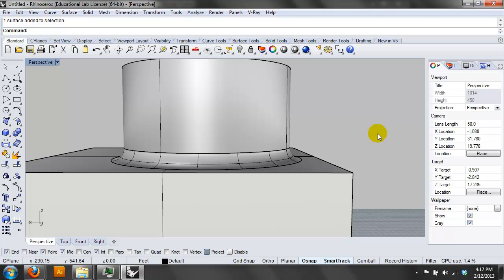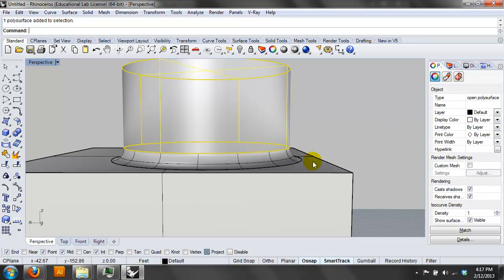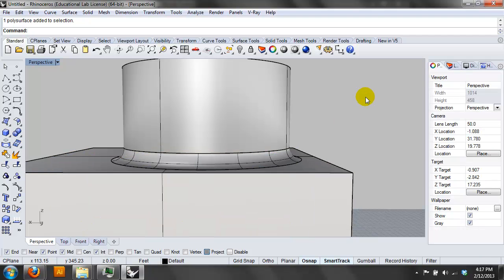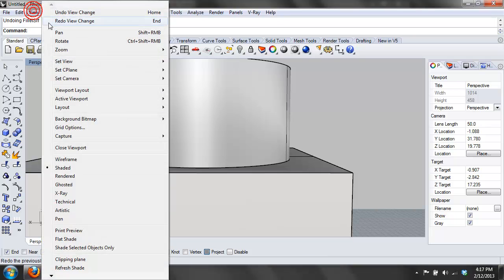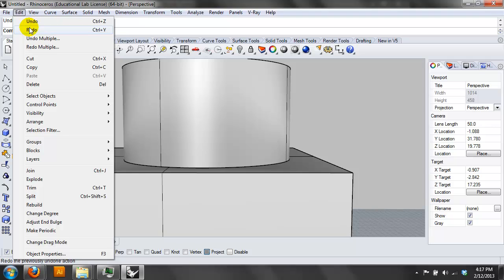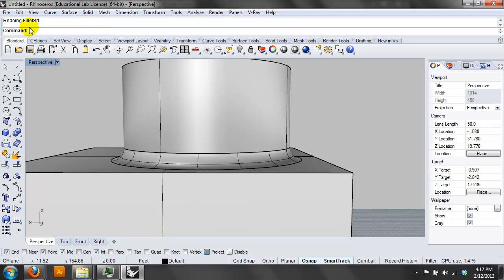What did we just look at before? Yeah, sweep it. Do a 2-rail sweep with an arc between the two. What would you do though? You'd actually have to trim this and trim this a little bit too, right? Because it started off like that. I'll show you here. Where's my redo? Yeah. There's a little bit of a trim. They actually sacrifice some of the material to get the fillet. Make sense? Okay.